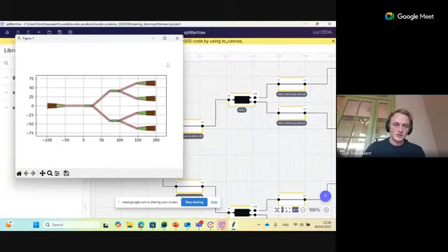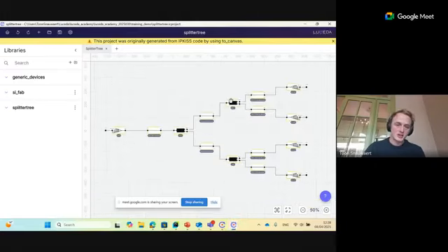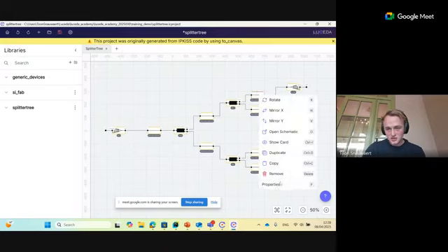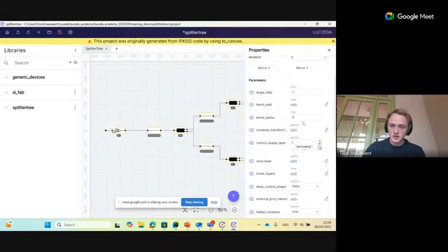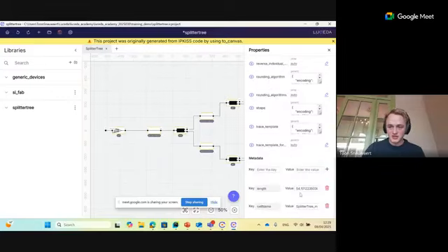And then we go back to Canvas and we can check if everything is well connected. And now you can see that there are these waveguides between these components. That is because now we didn't use Connect Logical, but we used the Connect Manhattan or the Connect Bend connector that creates actual waveguides. You can have a look in the properties of these waveguides, and you can see all the parameters of this waveguide connection, which bend radius it has, and also the length can be found in here.